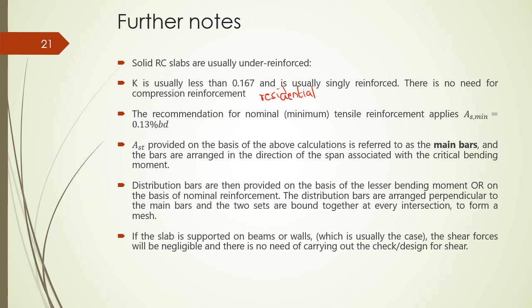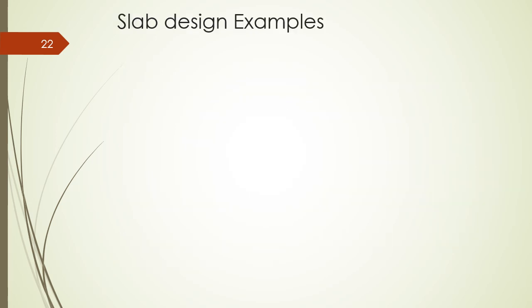If the slab is supported on beams or walls, the shear forces will be negligible and there is no need to carry out the checks for design for shear, that is, in slabs. The verification on deflection still applies.